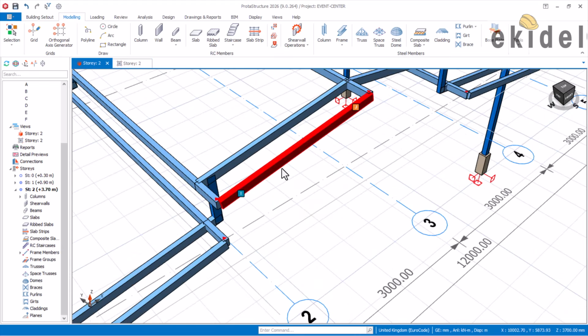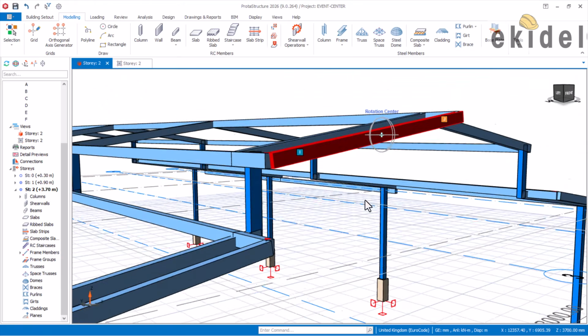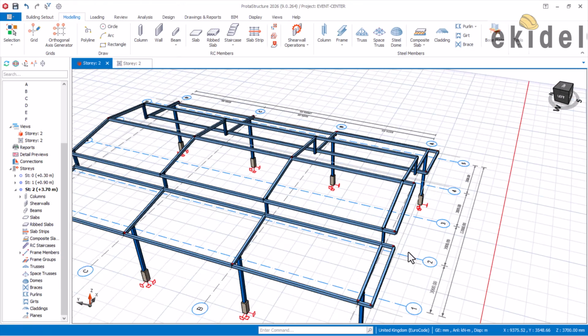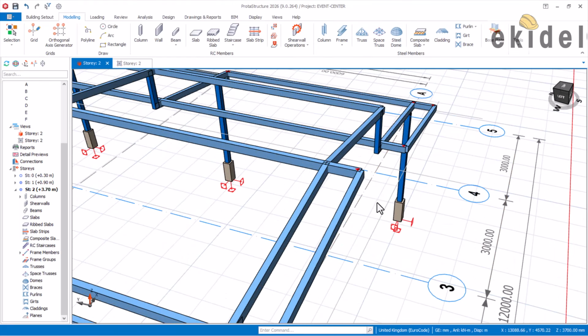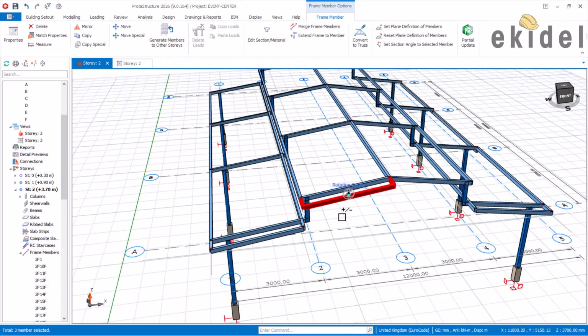Correct. So you can see that. When you are clicking, make sure you obey those insertion points. Okay, that is fine. So we have this now shown to us here. Then we click on this, hold our control key to copy this, then we mirror that to have this in this direction here.